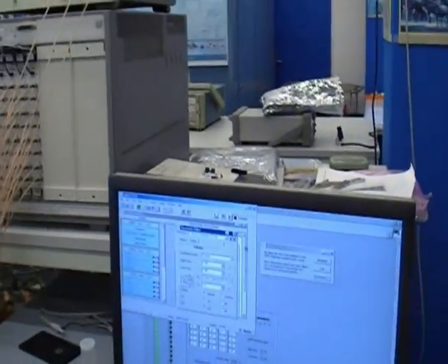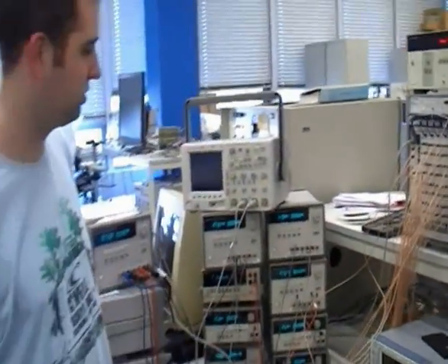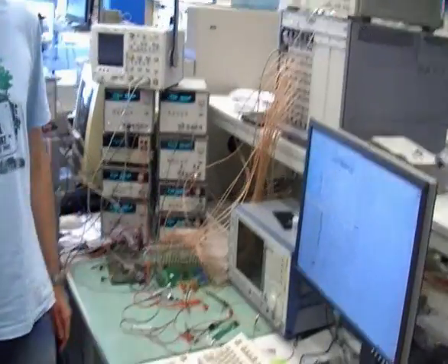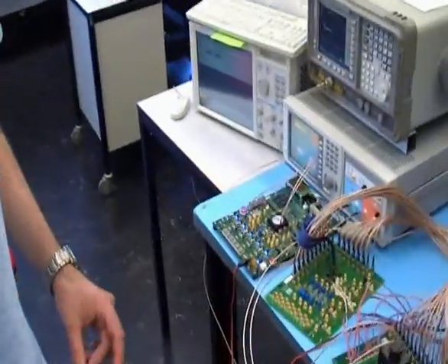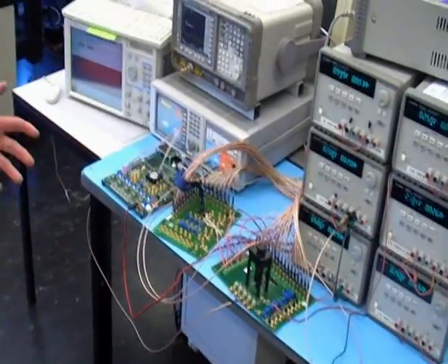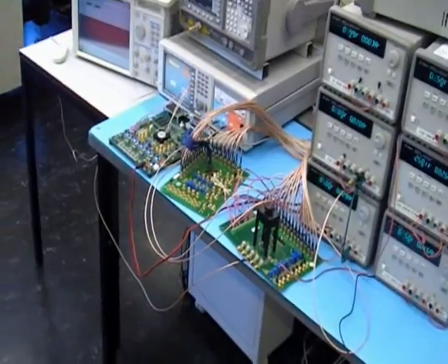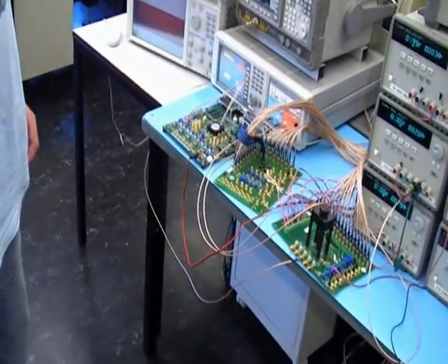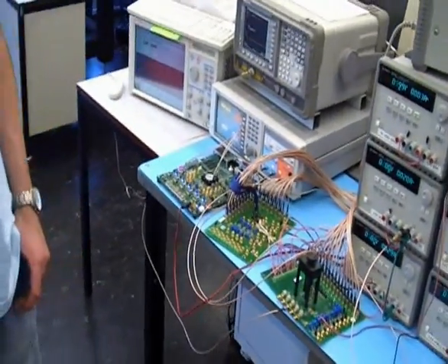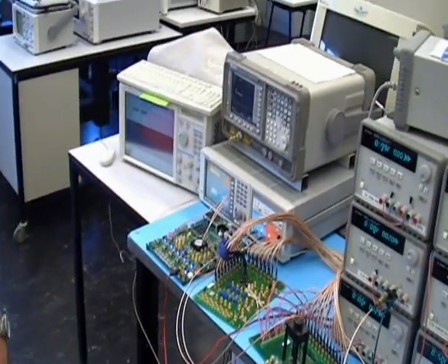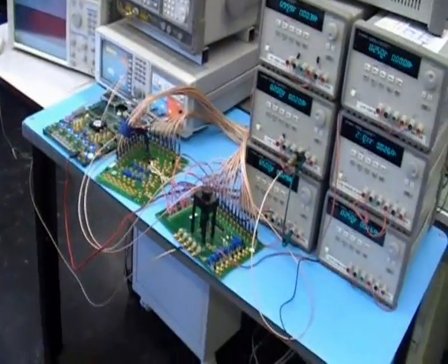These are the best levels for measuring this particular DAC, the optimal point. But the FPGA has a standard LVDS value. You can't change the level. It's the standard value, so you cannot fine-tune the analog properties of the digital signals according to the particular DAC.